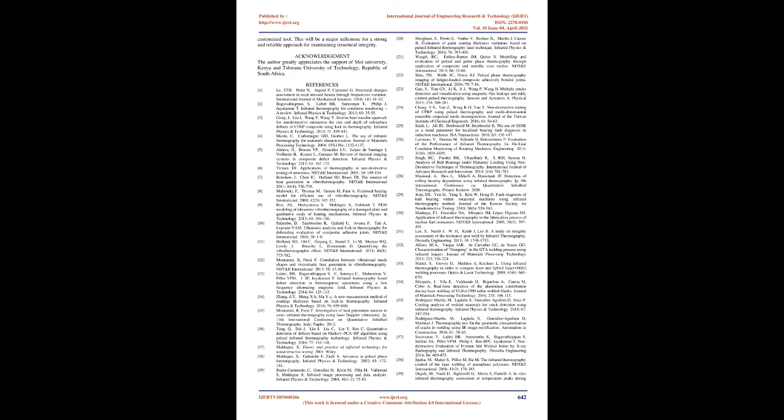Primarily, it is known that frictional heating concentrates within the real area of contact between two bodies in relative motion. Montanini and Freni 12 explained that the amount of frictional heat generated depends on several parameters, which include coefficient of friction, normal applied force and the sliding relative speed. However, this study kept other factors constant while the forcing frequencies, and hence relative speed, varied.